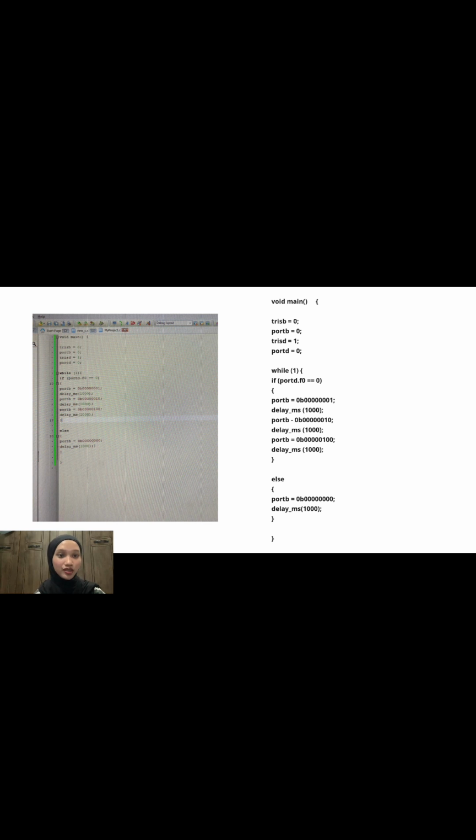Okay, so we can see on the slide the programming code for our project. Let me explain the port B and port D. The commands that we see in the programming, TRISD is for the input and TRISB is for the output. For the binary numbers used in the command, we have 3 same commands but with different binary numbers.